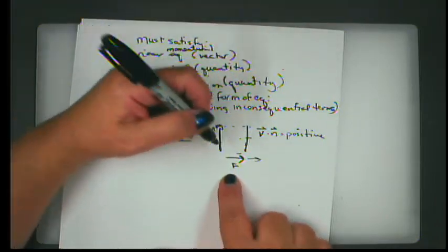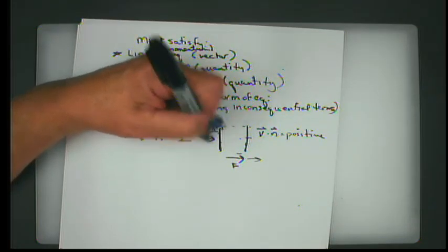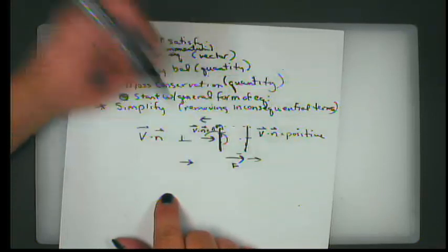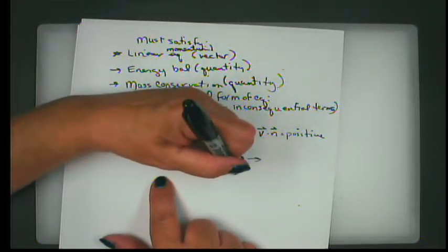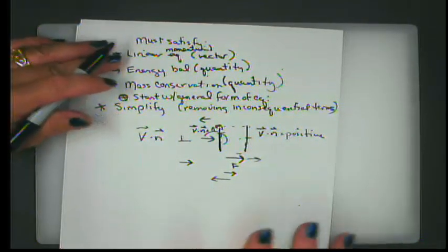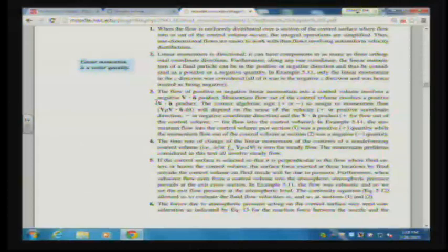So what it's really telling you is that mathematically it's because the angle is 180 degrees. But functionally what it's telling you is momentum in this direction will produce a force in this direction unless it's opposed by a reactive force, whatever the nature of that is. So to keep your sign straight, you need to remember that water coming into a system has a negative sign, and that water coming out of a system has a positive sign in terms of the momentum.